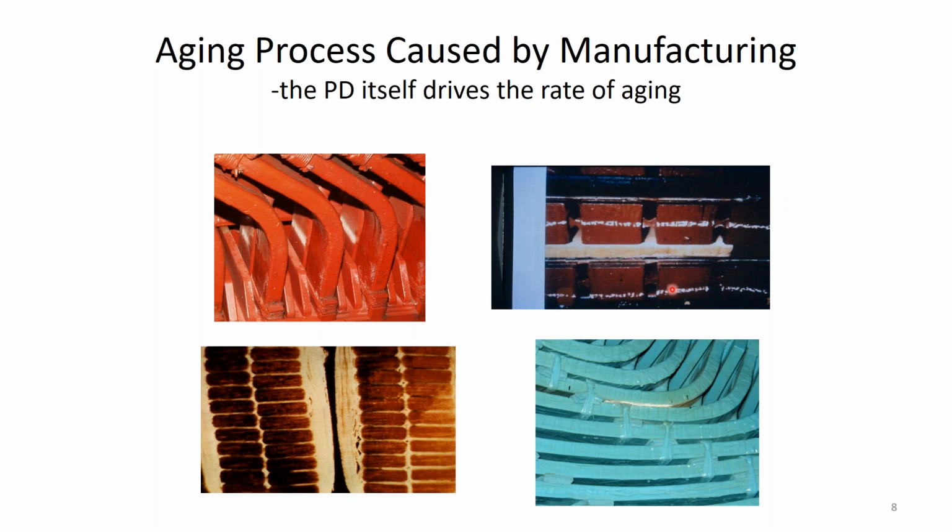Here's the stator core we're looking at. I've removed the wedges, and instead of looking at a nice shiny black surface like in this slot, you see the semiconductive armor has just disappeared. This is on a hydro generator, where the interface between the semicon in the slot and the stress relief coatings that cover the winding was not properly made, or the materials were not properly applied, and we get some discharges here.